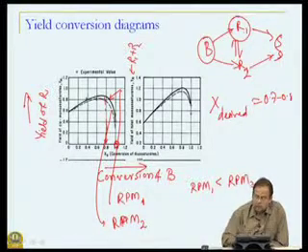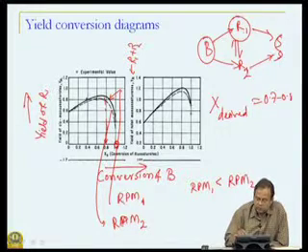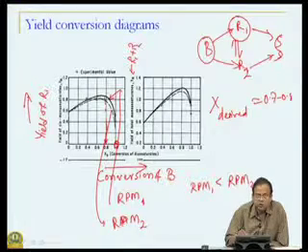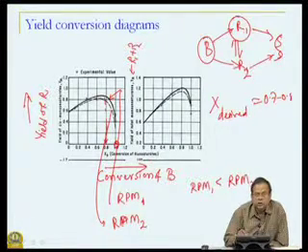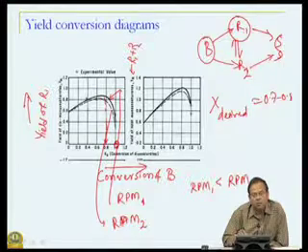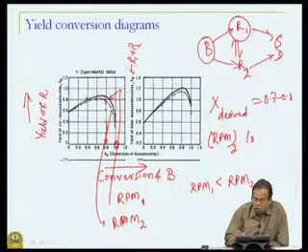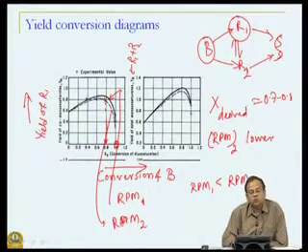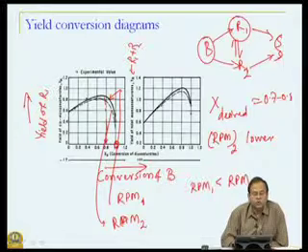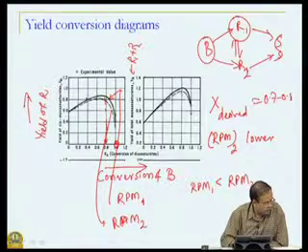So, another lesson that is to be learned from this example is that when you are trying to design heterogeneous reactors, achieving uniformity, the highest degree of homogeneity, or mass transfer is not necessarily always the design criterion. So, here among the two, RPM 2, the lower of the RPMs, is to be selected, because that gives you higher selectivity.